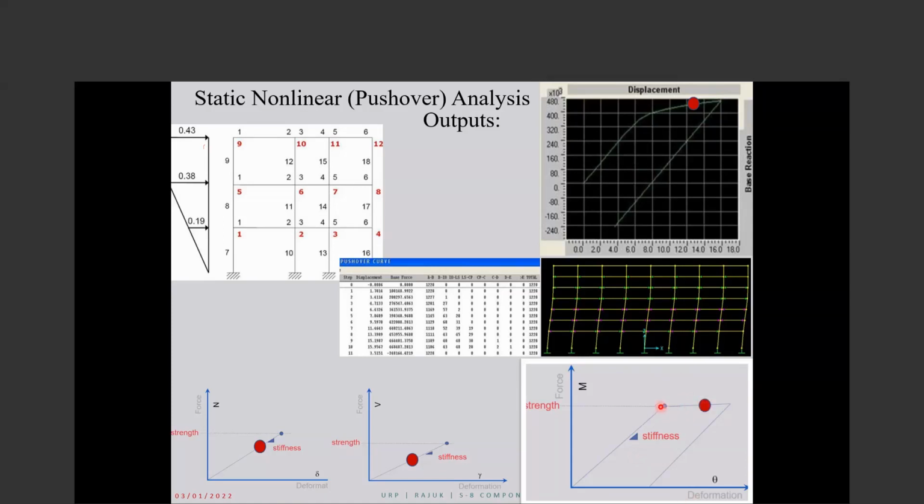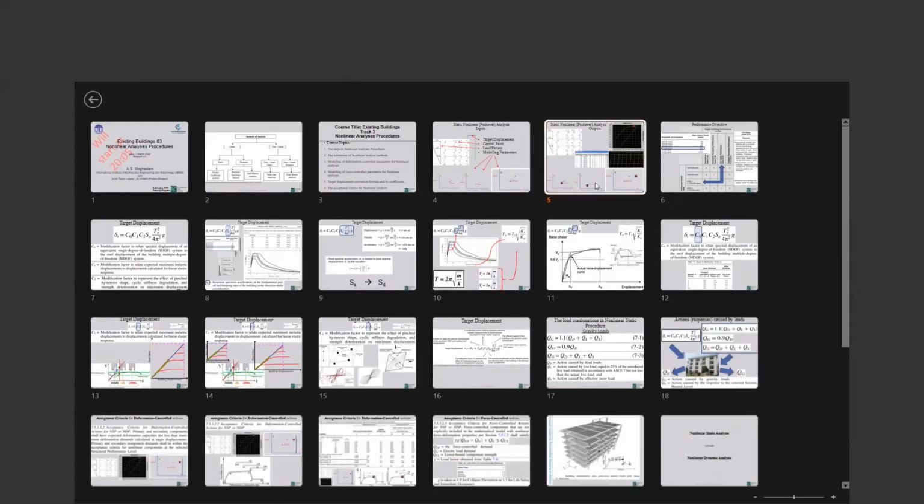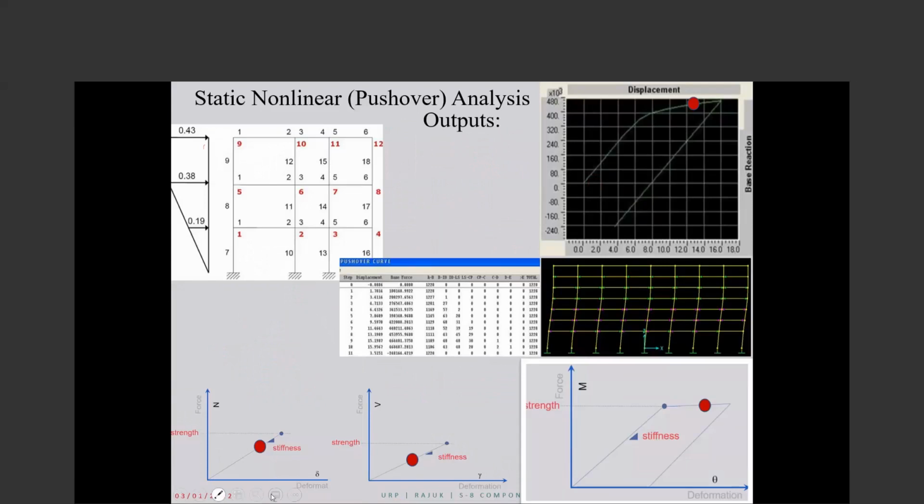They didn't pass the plastic deformation capacity. But the stiffness of this element is not this much anymore, it is 0. So the contribution of the stiffness of this element to the building stiffness is gone. So the building stiffness reduces. And little by little, the building stiffness reduces because more deformation control elements get damaged till it comes to this point. And then the software can also give us some output, this one.